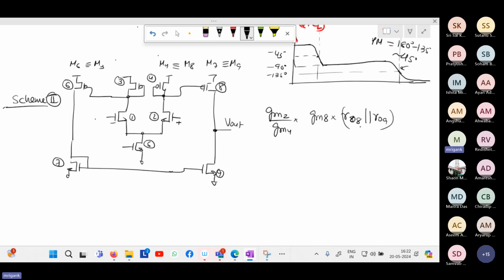So what he has done is that you've got the signal at one side. Whatever the signal, if you assume the half circuit, this is AC ground, then whatever VD you are having, VD by 2 will appear here, half of the differential signal.